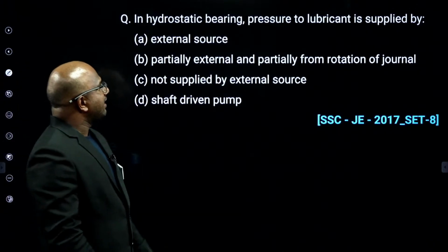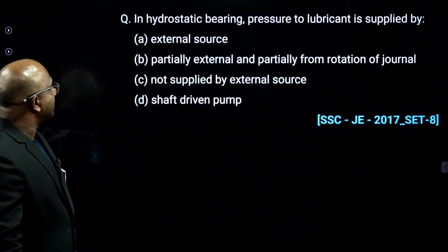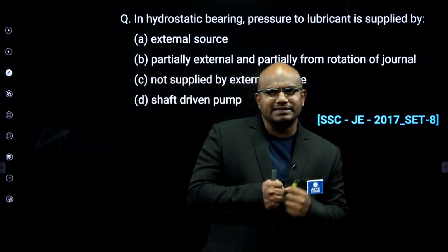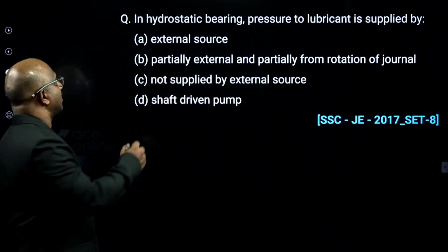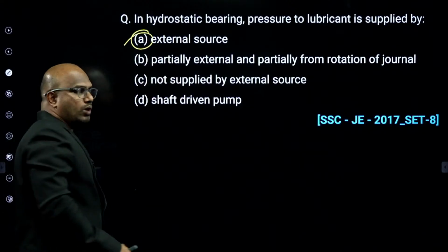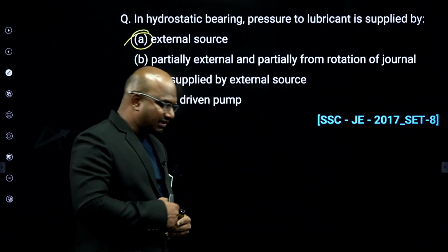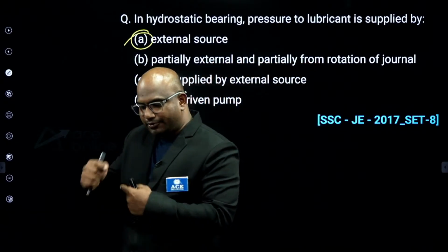In hydrostatic bearings, guys, the pressure to the lubricant is supplied by? So in case of a hydrostatic bearing, who will supply the pressure to the lubricant? Think about it. It is due to an external force. Some external source is required to supply the pressure to the lubricant, guys. In case of a hydrodynamic bearing, it forms a thick film due to the friction.